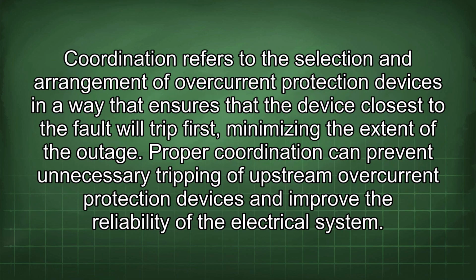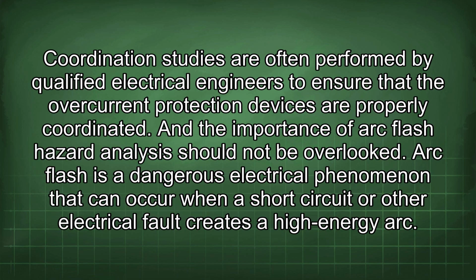Coordination refers to the selection and arrangement of overcurrent protection devices in a way that ensures that the device closest to the fault will trip first, minimizing the extent of the outage. Proper coordination can prevent unnecessary tripping of upstream overcurrent protection devices and improve the reliability of the electrical system. Coordination studies are often performed by qualified electrical engineers to ensure that the overcurrent protection devices are properly coordinated, and